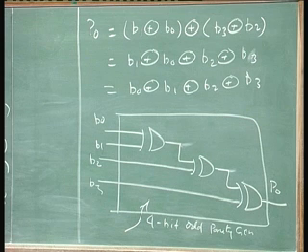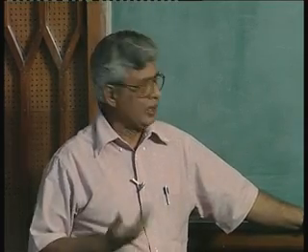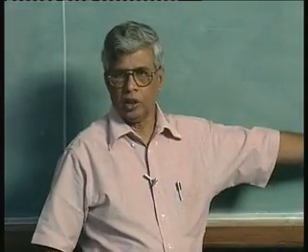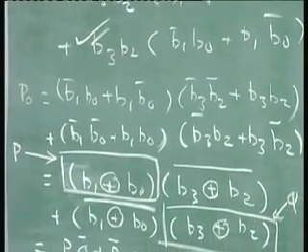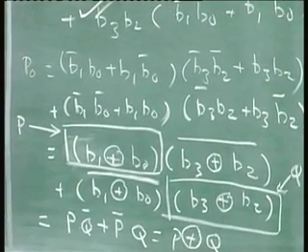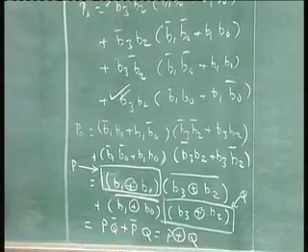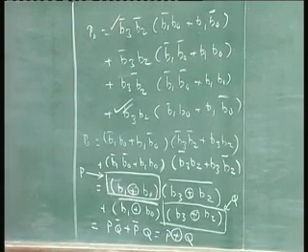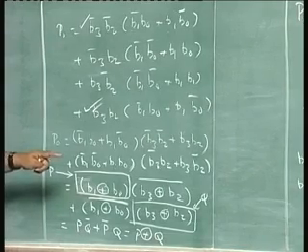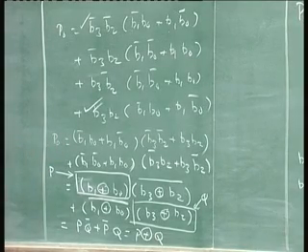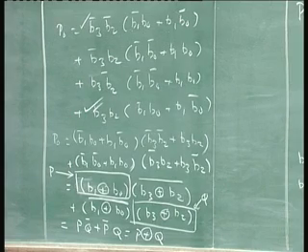So I am only picking up those circuits, but the concept of design is the same. Starting with the problem specification very clearly defined, going to the truth table, to the Karnaugh map, to the simplification and hardware. Sometimes from the minimum sum of products you can directly implement this logic, sometimes you may have to do some extra manipulation, as in this case. We also saw this in the case of the Gray code generator, some sort of grouping helps in reducing the hardware further. This looks so formidable, 8 gates each with 4 inputs and inverters for each one of them, followed by an 8 input OR gate, whereas now this is so elegant. So that type of thing also sometimes is possible. As I said, the last of these examples we will take today is called a 7-segment display decoder. Again we will say BCD to